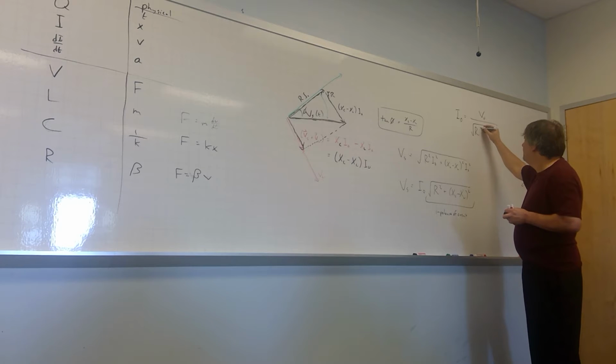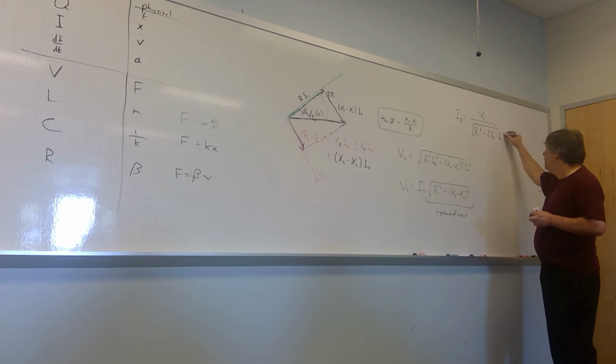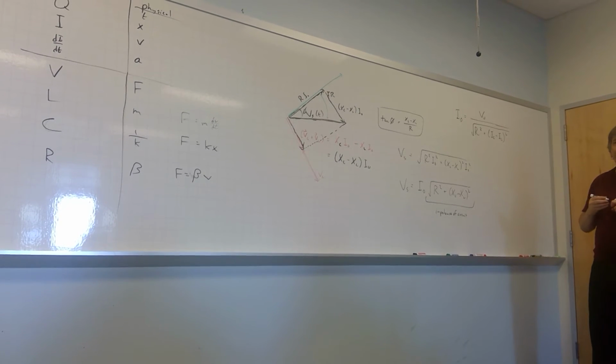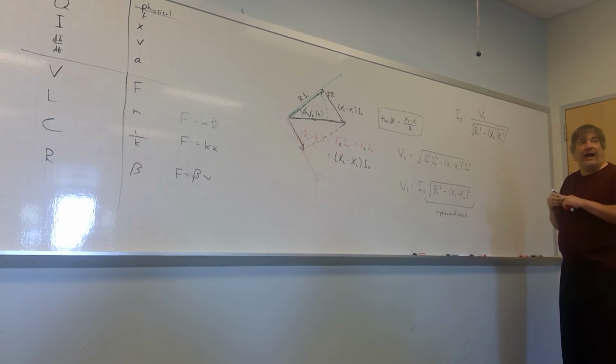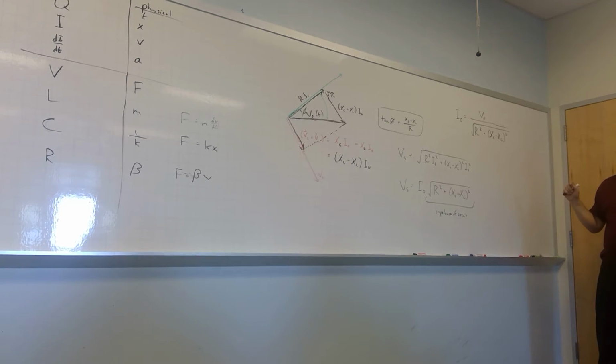Decrease the frequency. Decrease XC and XL. I could try to decrease XC down to 0. I could make the capacitor a zero impedance device by turning the frequency way up. Do I want to do that?